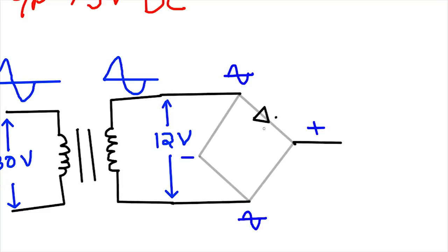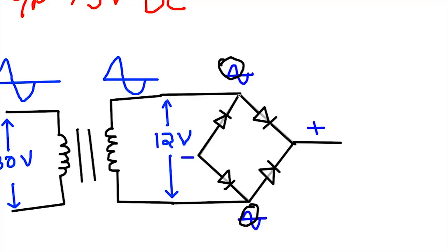So if I place the diode in this direction, positive half cycle would no doubt flow through this. Same is true on the other end of the AC terminal. This way we would get the positive half cycle in one side, and for negative cycle we just need to place the diodes in the reverse direction with respect to its opposite diodes. Just like this.